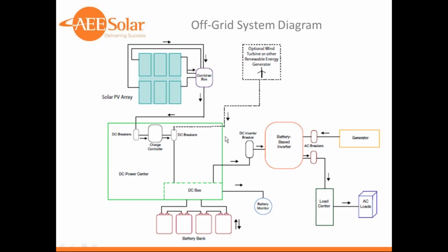But everything that is connected to the battery must go through a DC-rated circuit breaker rated for the voltage of the system that it's operating on. Batteries can dump enormous amounts of current into short circuits and melt things and start fires. So every connection to the battery needs to have overcurrent protection on it.